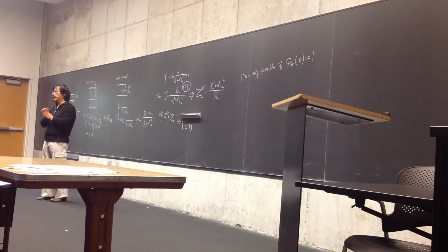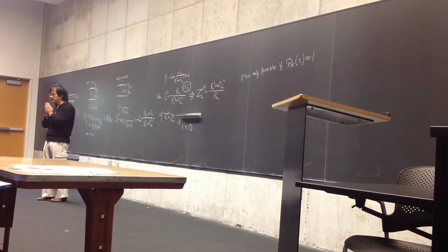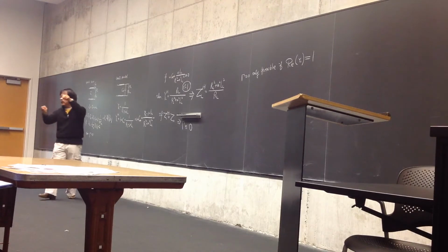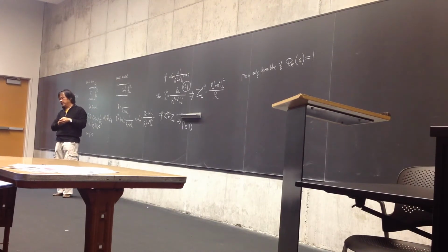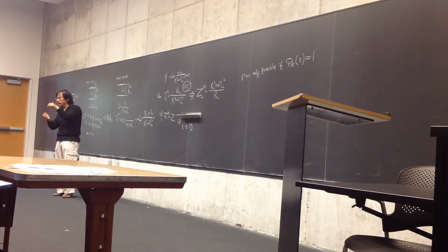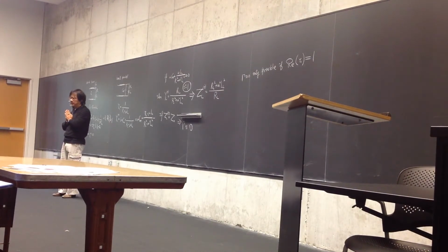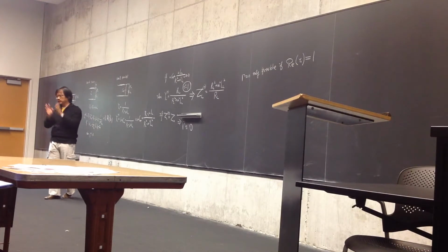So you see, that's what I was joking to you guys about, is that when you cannot solve the problem, you change the problem. So I want you to match this transmission line, and if you want to match it right at the location of your load, you cannot do it. You change your problem. Find where you can do the problem. In other words, you move around your transmission line to find the location where the real part of your admittance is equal to 1. And that will be the location that you're going to add the circuit component. So you see, very good. So you actually follow me good.